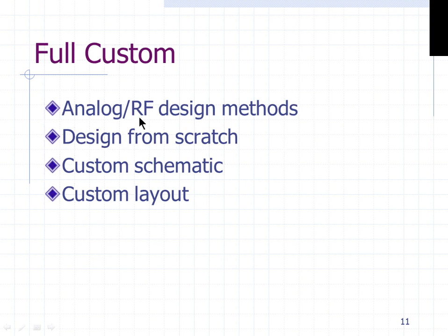Analog part is where your RF will come into the picture. So for any analog part or any mixed signal IC design, normally people have to do some work at CMOS level, and when you have to work at a CMOS transistor level, that is where you do full custom IC design.